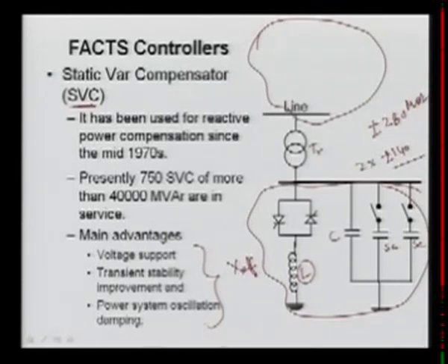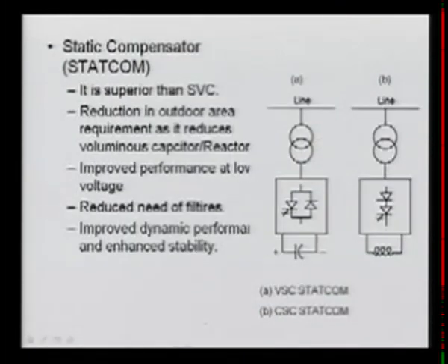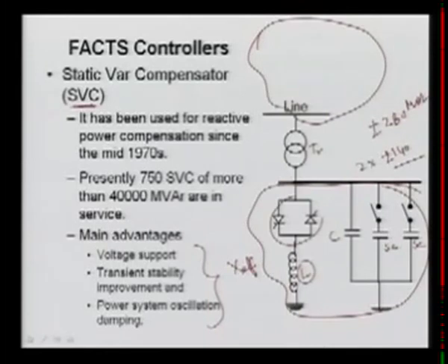However, another shunt device is your STATCOM, that is called static synchronous compensator, or STATCOM simply. It is superior to SVC. The reason is that it is a converter based technology. If you see in the previous one, it was simple anti-parallel thyristors. It is not a converter.